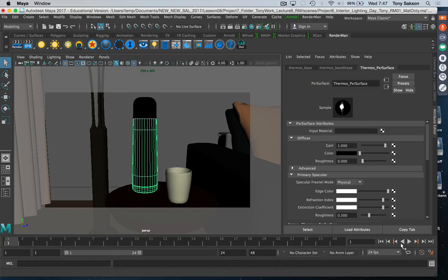Black. Right, because remember, when we shut reflectivity off here, we pick up the leftovers from here. Remember, Pixar surface tries to be what we call physically accurate as far as conservation of energy. That means if you've got a lot of reflectivity, you've got very little diffuse. If you've got more diffuse, you've got less reflectivity. If you've got transparency, it shuts off the diffuse and the reflectivity. It tries to maintain 100% energy efficiency. That means you can only have 100% of the energy in any one place at any one time.